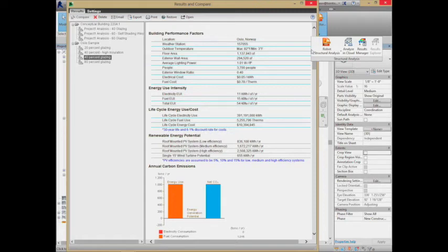You can start seeing how much fuel we're using, typically for heating, how much electricity we're using, often for cooling and lighting and plug loads and all those different things. You also have this notion of how much we think it's going to cost over 30 years to heat and cool this building. So about $10 million here, over a 30-year lifespan using 6.1% discounting.